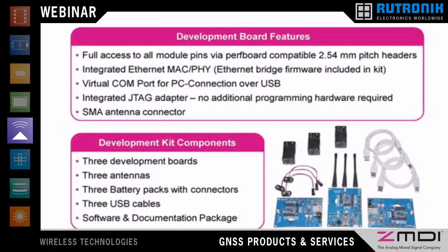Let's continue with the software. All the software for the module is royalty free, so you get an API library. With this, you are able to develop your own application. Here you can see the structure of our software. We have some libraries supporting the interfaces like the UART or the SPI. We also have libraries with IPsec and the key exchange module, and we also have the 6LoWPAN library that allows you to communicate via UDP.